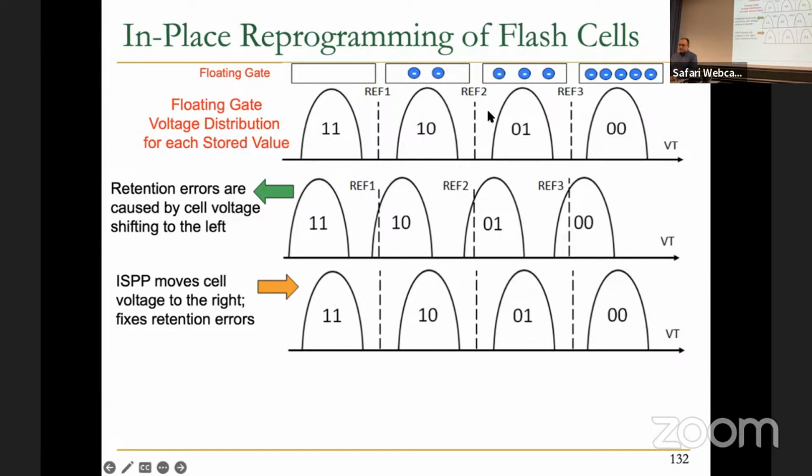People have used this idea also to provide in-place update in flash memory. But that's not very easy to implement, and it also comes at the price of some errors. For example, they consider that they are using TLC NAND flash memory, but they only use the 4 initial steps of it.